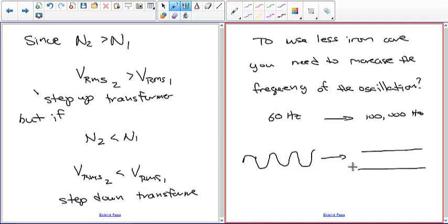So you take four of those little diodes that we played with in the lab, that we used to protect our motor. And you can basically come out with a DC signal. It's not flat, but it's all positive. Then you put a capacitor in there to smooth out the wrinkles in the signal. So you end up with a DC source. That doesn't take too much electronics, not too fancy.